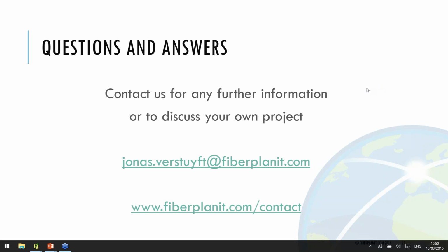One question I see here is, is it possible to load existing information about existing ducts and define a rule to prioritize the use of these ducts? In FiberPlanIT, you can load in existing duct information. That's not something that we did in the demo here, but you can load in this information, and then in the design rules, you can specify the different unit costs for using an existing duct, for using an aerial line, and for doing new trenching.